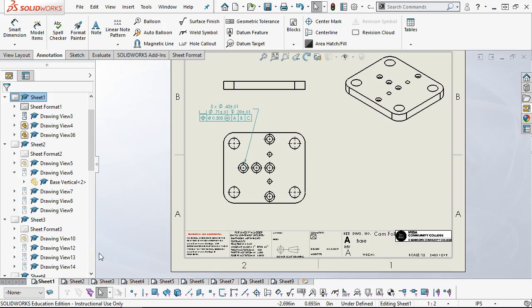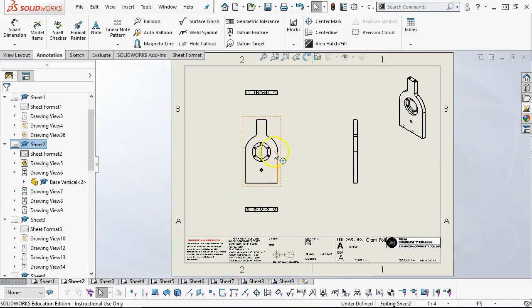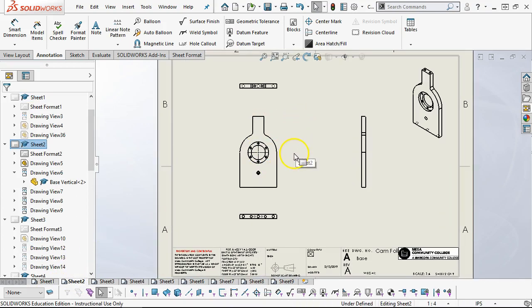All right, so you can use that for reference, but obviously the tolerances are a little wide open here. So I want you to think about what's going to be realistic for flatness, parallelism, the perpendicularities, the positional callouts, and again the pin locations and the pin sizes for a light press are going to be our critical dimensions.